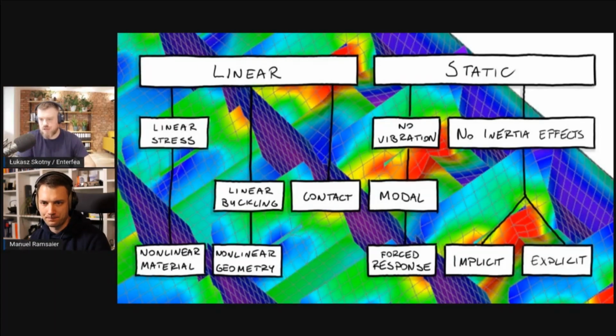And somehow when I talk about fatigue, engineers instantly know what fatigue is. Everybody is careful about fatigue. So maybe stresses aren't as high as yield or whatever limit I am willing to accept, but I still have to pay attention to fatigue, because you can do this in a linear way in some sense. Fatigue is manageable in linear analysis. You just check the differences between maximal stress and minimal stress in each cycle, and you can do something with this information from linear analysis. And when you do linear stress analysis, the stability is just not there.